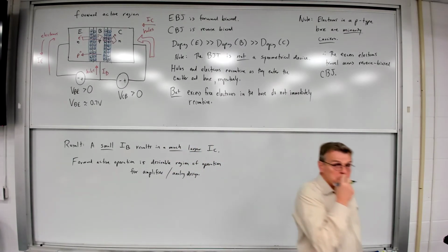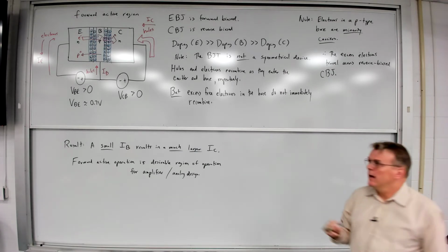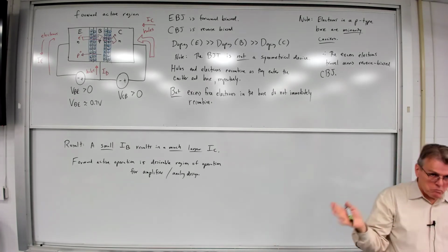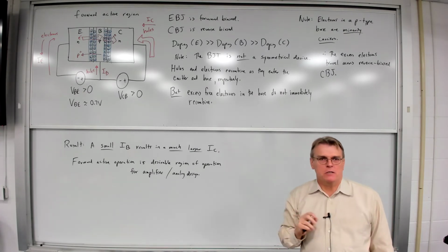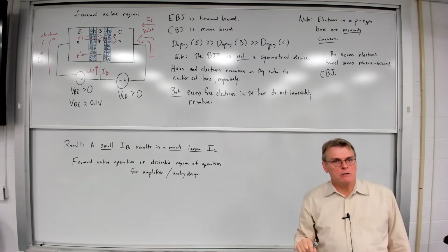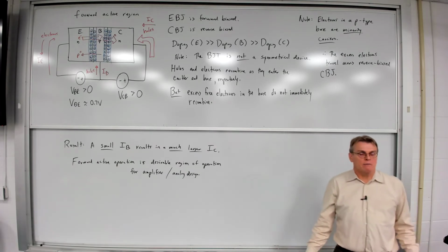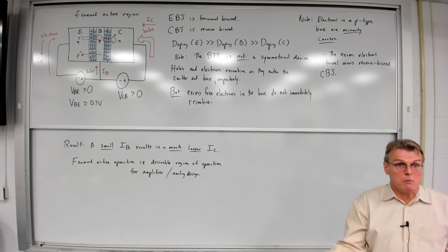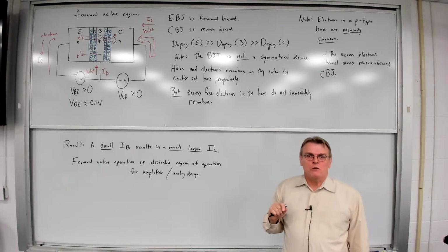So, as we're going to see, most of the practical circuits we're going to build are going to be in forward active operation. Now, for reasons we're going to talk about later on, bipolar junction transistors make perfectly good amplifiers. They don't really make good switches. You can take a MOSFET transistor and push it into the triode region and make it behave like a switch with VDS goes to 0, and it works perfectly well that way. In fact, that's why all of our digital designs nowadays are based almost entirely on MOSFET transistors. Bipolar transistors don't work so well.